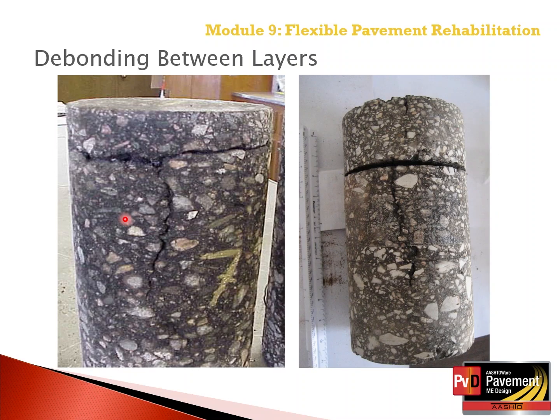Debonded layers near the surface cannot be detected without the use of cores. Surface modification without structural overlays could be an option considered for both of these projects based on magnitude of cracking, which is low, and the severity of cracks, which is also low, of the surface cracks. Basically no surface cracks here. Very minor top-down cracking at the surface here.